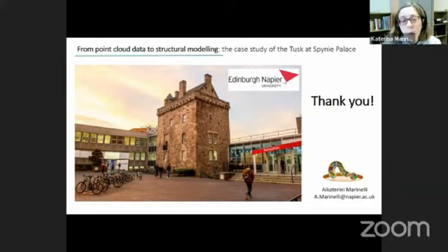So the masonry was in a bad condition, so it could not be accurately estimated. So I collected data from the actual material that was used on that structure, although the vulnerability and the weathering conditions could not have been quantified. And then I compared that with guidelines from the literature, as well as the Italian building codes, which were a good source of information. And then the values were approximated, and we took a range of values anyway to be able to have a reasonable estimation of the mechanical properties.